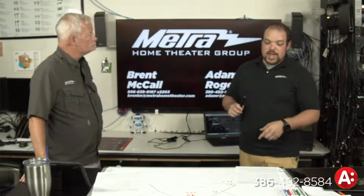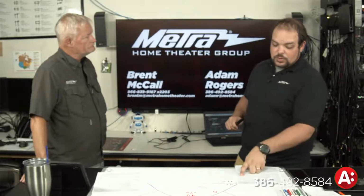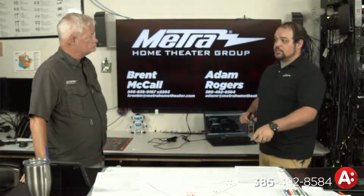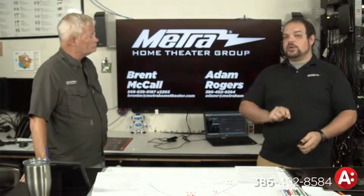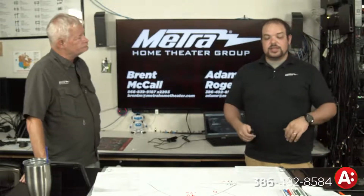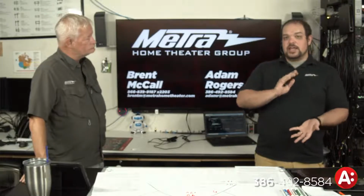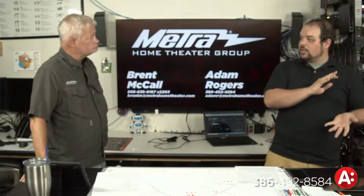But what will happen is that if you have the Class 2 or the PoE Plus, you will see a 14.5 to 20.5 voltage from the PD first. And that's just to verify, are you really PoE or are you PoE Plus? Kind of, yeah, exactly. Then at that point, it does a startup voltage, which is greater than 42 volts, and that's to actually get the system powered on. It's that inrush of power, so they can go ahead and get started.